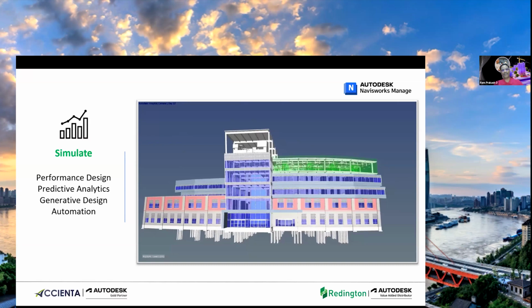There are add-ins available, named Issues add-in for Navisworks and Issues add-in for Revit. So what will these do? Say I'm viewing a model in the cloud using BIM Collaborate Pro, and I want to tell my mechanical engineer to optimize the duct because it is clashing almost under the beam.